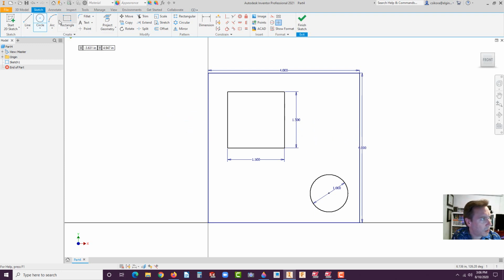All right, now let's go to the line tool and infer over here. Click and drag this out. Don't put any dimensions in. Drag this across. Oops. Make sure I got a couple of fragments in there. You don't want fragments in your geometry. I'm just going to delete that line and start over. There we go. And then basically you're making a triangle.